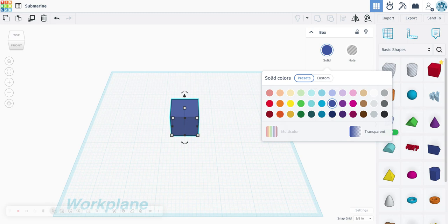The color of your 3D printed project depends on the color of the filament or plastic tubing that you use inside the machine. So the settings for the machine are going to all be based on the machine and the product that you put inside the machine. What we're doing is creating a three-dimensional model that's going to tell the machine what shapes to print, but it cannot tell the machine what colors to print. And so that has to be told to the machine on the machine settings itself or in your slicing tool, which we can get to later.